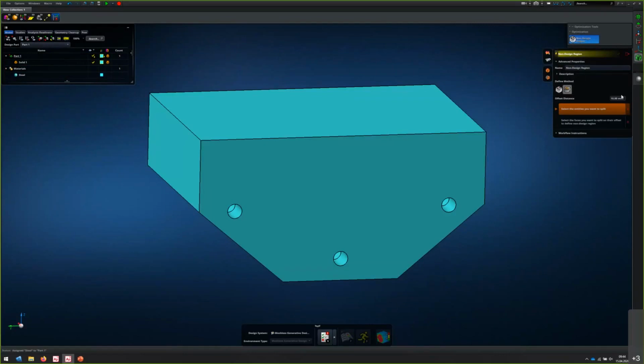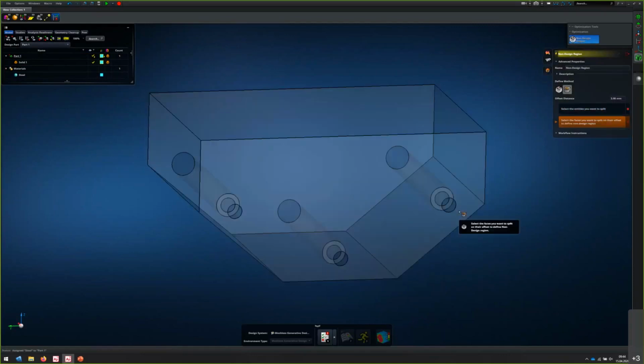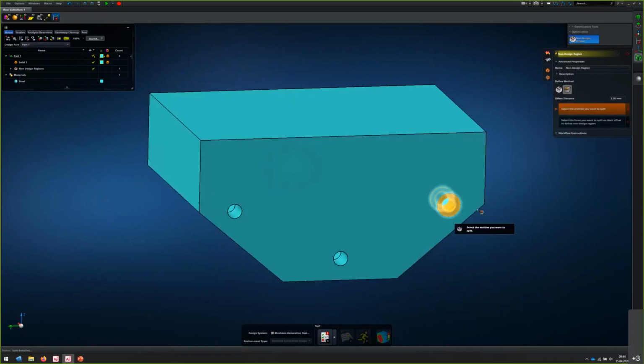Probably a lot of you already know this, but in generative design, usually we create non-design spaces and not just put loads directly on surfaces, but on volumes. The reason for that is that this method creates better transitions between the non-design and load application points than just using the surfaces. And of course, if you want to do additive manufacturing afterwards, you also want to be able to post-process some of these areas, and therefore you need a bit of material in these areas.